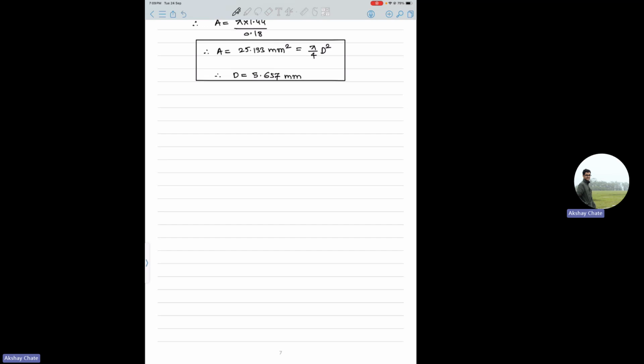and the deformation that takes place in the workpiece, which is not actually undergoing the welding process, because of high heat transfer. Because you should understand, it's a very localized melting process, but the heat transfer will take place within the body of the workpiece. It will not melt as a whole, but there will be temperature changes. Okay, that is why this heat affected zone comes into the picture.